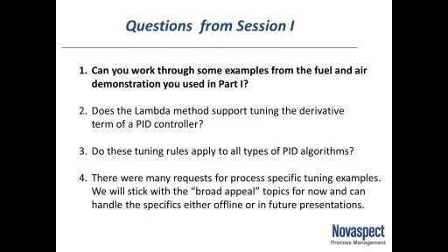The third question was, do these tuning rules you presented apply to all types of PID algorithms? And my answer is almost, not quite. There are 3 main popular forms of PID control algorithms out there. Each one requires slightly different tuning. Most modern digital controllers today use what we call the standard form PID. You might also hear this referred to as the ideal, the non-interacting, or an ISA form PID controller.